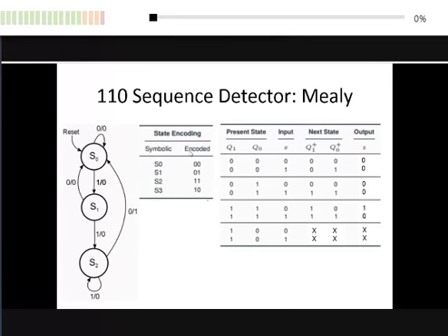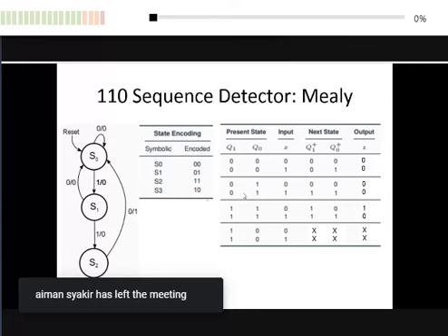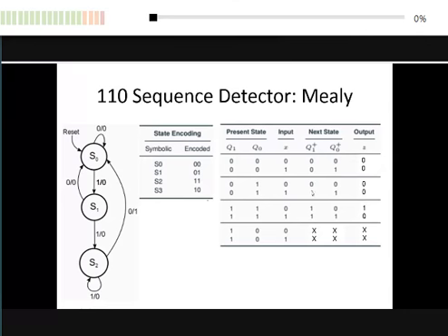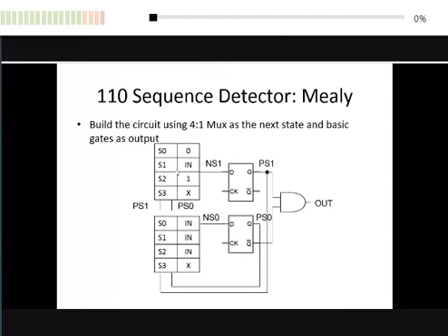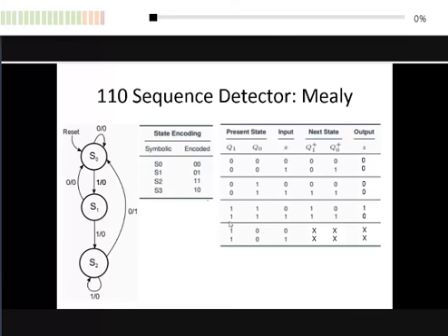Okay. Now when present state is 0, 1, the Q1 plus is 0, 1. So it follows input in 0, 1. So might as well label it as in. So that's why in S1 I label it as in. Let's see S2.